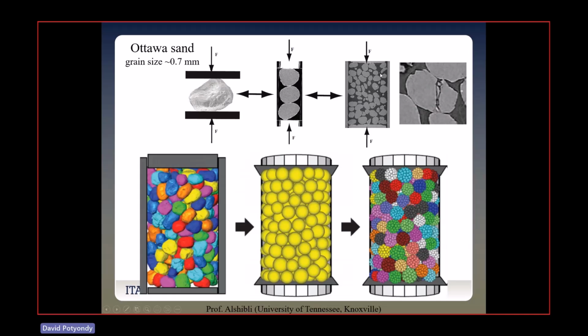And here you're seeing about 20 of those in that triaxial cell being compressed. And here you're seeing in great detail one of those sand grains being compressed between 2 other sand grains, which is kind of like a Brazilian test, which is splitting it down the middle into a bunch of things, because you can actually see internally it didn't make a single fracture. It made little grains in there too. Okay.